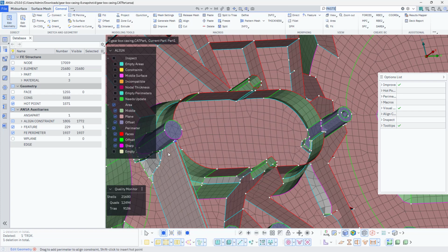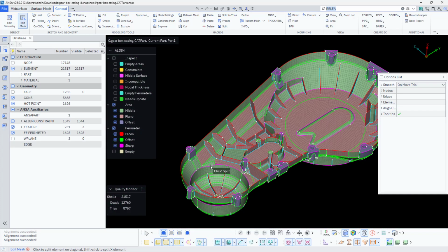Yeah, so this is all about fixing the mounts, whether it is manual or automatically created. So these are all the steps you need to follow. Now once you're done with everything, you could see we have fixed all the mounts and all the perimeters and some of the regions with mid mesh, and some of the regions we have neglected, which is not at all needed for us as per the requirement.